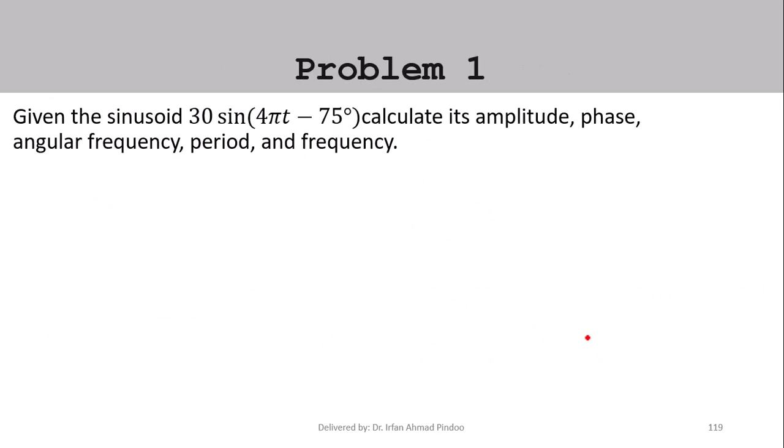Now the last thing we will be discussing is two numericals based on AC analysis, the type of question you can expect in the numerical part. Suppose we have a sinusoidal signal given. We are asked to find certain parameters like amplitude, phase, frequency, period, angular frequency. In all these cases, you always have to equate the given equation with the general equation, which can be Vm sin(omega t plus minus phi). It is not specified whether the question is talking about the current or the voltage. We can also assume it to be Im sin(omega t plus minus phi). Both can be applied.